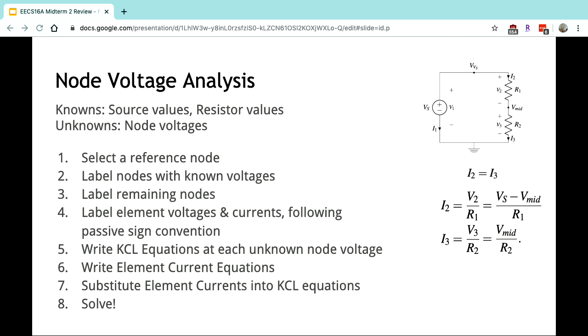In this case, we can take the input current I2 as the difference in the voltage nodes across that current divided by the resistance. And then repeat this as well for the R2. After that, we substitute it back into our initial KCL equation and solve it. This will give us our voltage. Once you find the node voltages, you can go back and calculate any currents you need to. In this way, you can solve for every current and voltage going through your circuit.